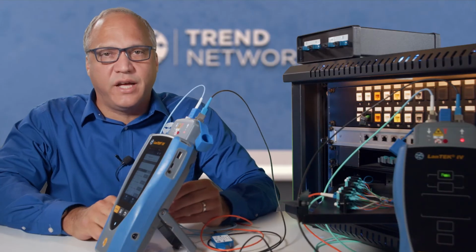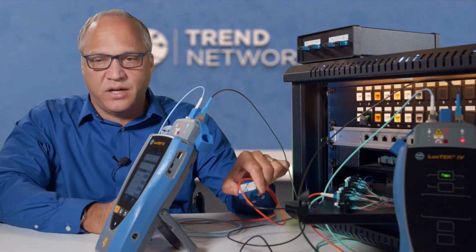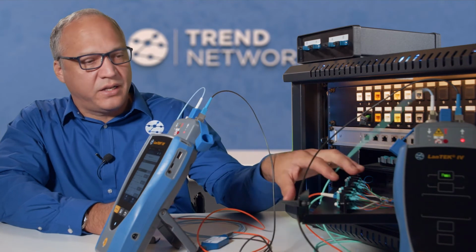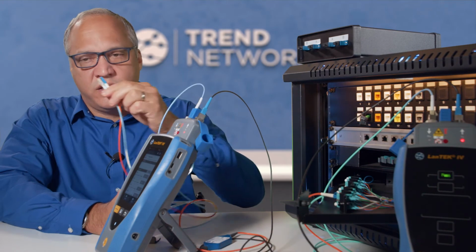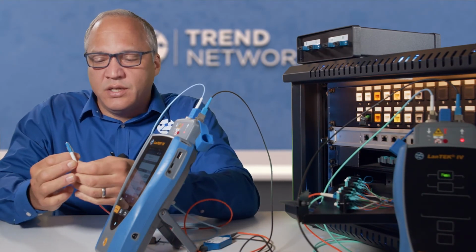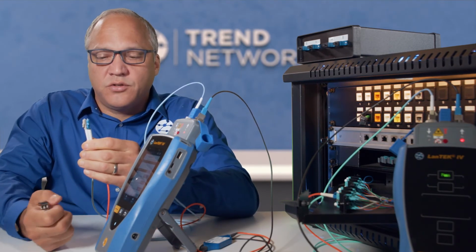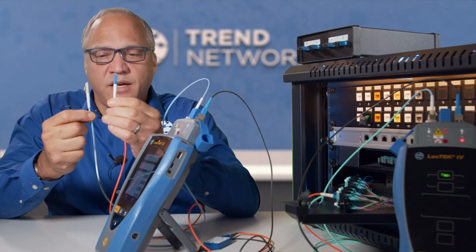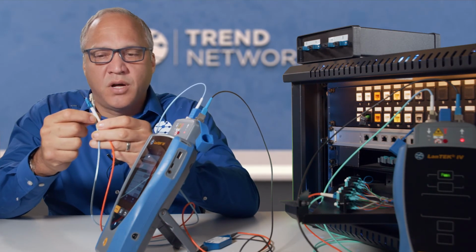So we now have the FiberTEK set up and calibrated with our encircled flux launch cords. I've already got the remote handset connected at one end of this LC fan out cable. And on the main end, I wanted to demonstrate to you which end should go on which fiber you're testing. The receive cord, so this blue cord, is going to the receive port of the LANTEC, and this orange cord is coming from the transmit port from the encircled flux module.